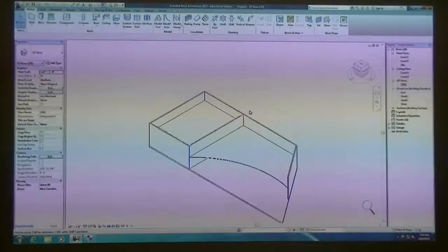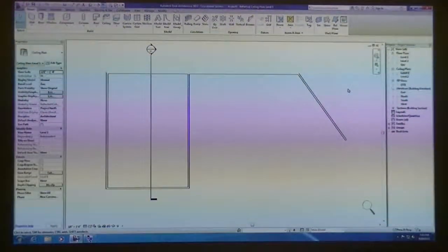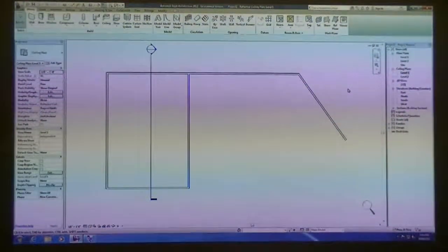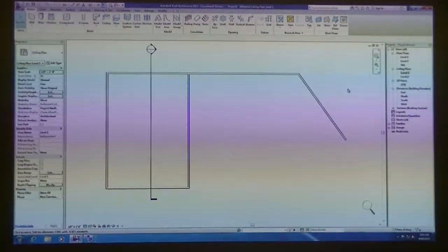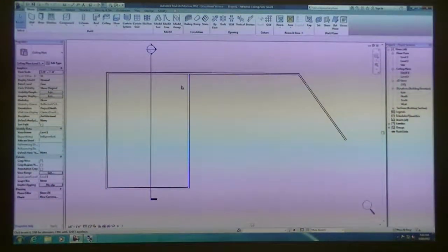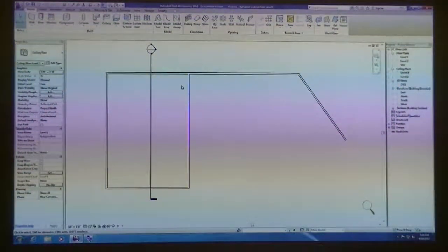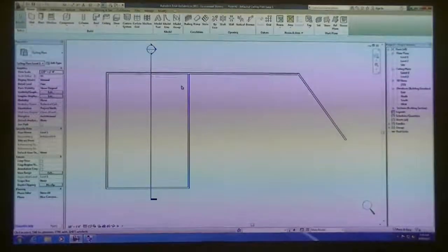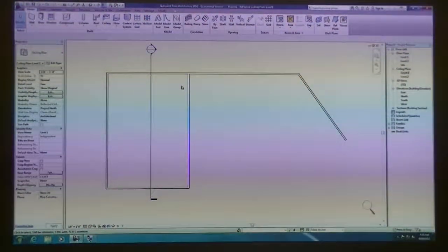The last part I want to show you is the 2x2 system, or any kind of ceiling that might be something other than gypboard. Everyone kind of thinks that, well, we'll just put gypboard everywhere, and you'll never find a building that has gypboard all throughout the whole entire building. First of all, that's very expensive. Number two, you end up having to put in access panels all throughout the gypboard ceiling that looks really ugly,